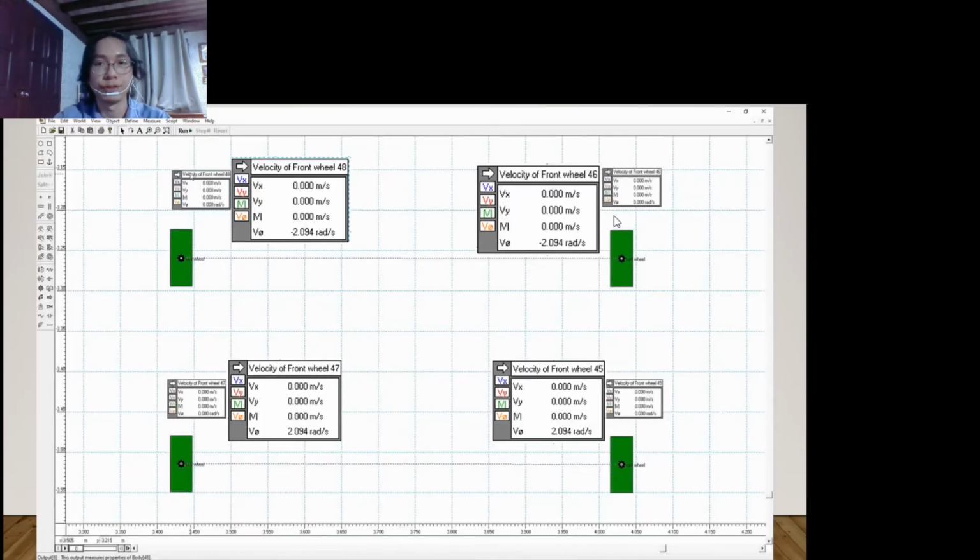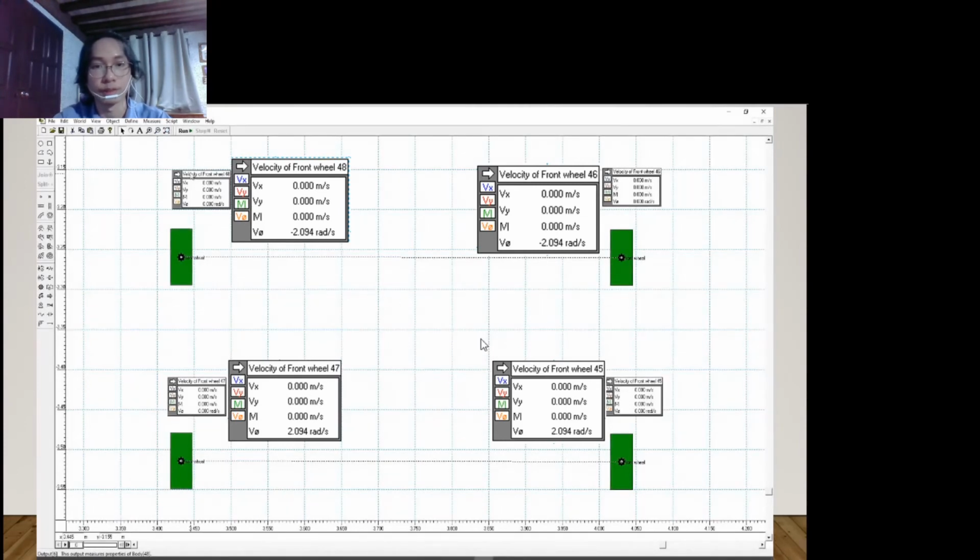These two green rectangular shaped parts are the wheels, the front part of the wheelchair, which is viewed from the top, and they are responsible to steer the wheelchair. This upper animation is the wheel rotation to turn the wheelchair to the right, while this bottom animation is the rotation to turn the wheelchair to the left. This steering mechanism is using a belt drive.